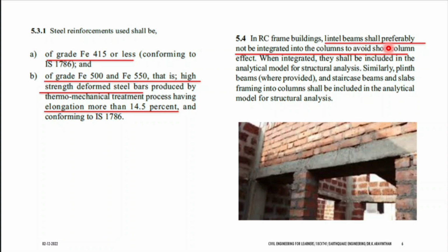Why? Because you have a beam. If you have beam like this, you see one column and second column. You see two columns in this. Practically speaking, this is not one column, this is two columns. Short column attracts more shear force. That is why there are many failures around the window. If you have done that, then the code says what you should do.